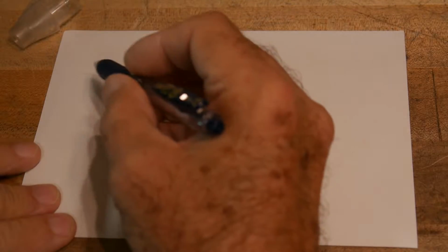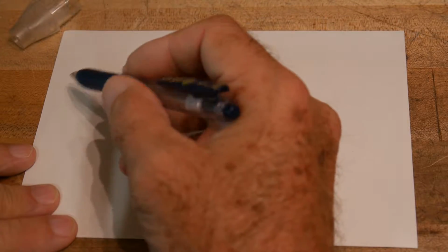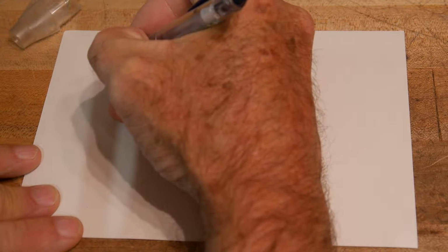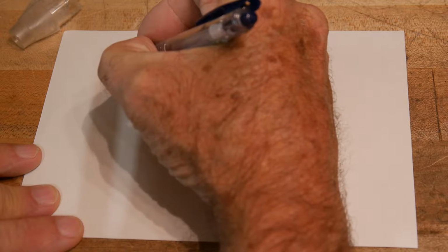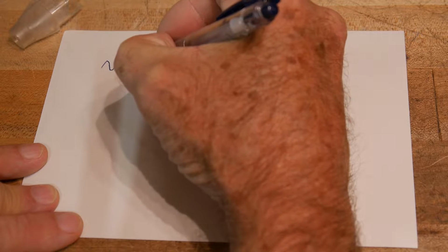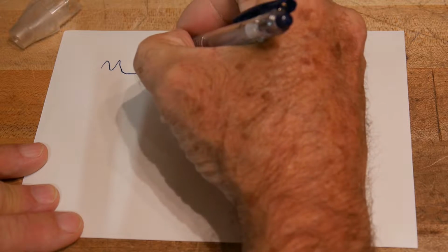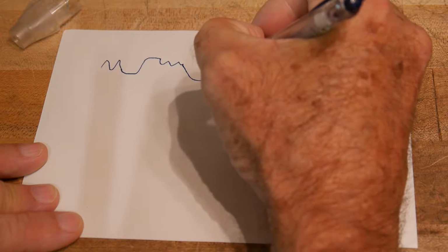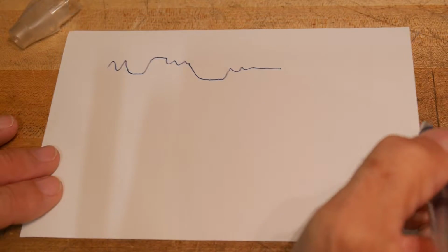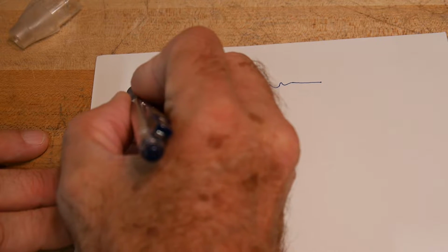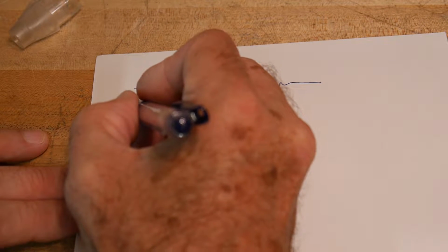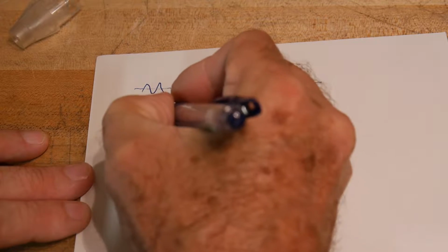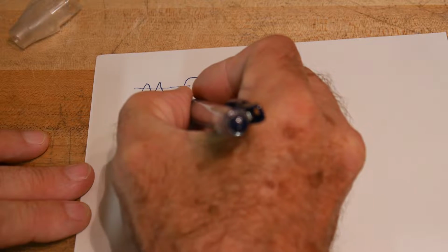All right, so we had a barcode tag, and we have an analog output. That analog output is going to swing up and down, and there might be a wide one, and then it might be narrow, and then there might be a wide one. What you want is a threshold that allows this to be a 0, then a 1, then a 0, then a 1, 0, 1.